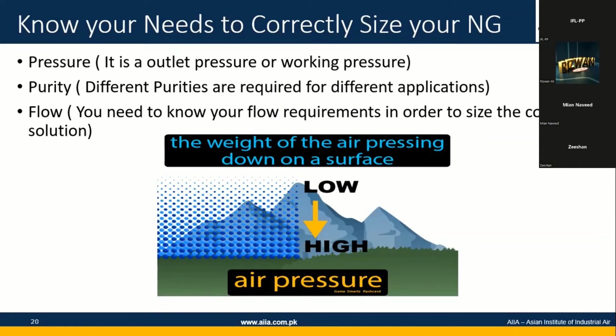If you want to correctly size your nitrogen generator, most of the companies and manufacturers have their own calculators, right? For the sizing of the right generator, they consider some other parameters as well, like the temperature at the inlet and the pressure at the inlet. Pressure and temperature at the inlet play a very significant role in the final free nitrogen delivery, right? The flow really depends on the temperatures and the pressures at the inlet.